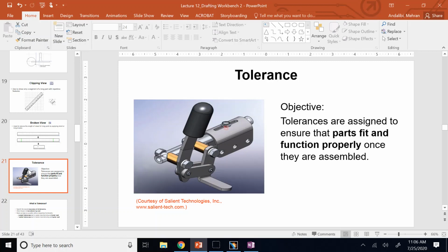So if it's very marginally off, it can still work, but probably you see what we call clearance and a little bit loose of connection. But maybe that works, maybe not, depending on how much you're allowing the manufacturer for inaccuracy. They have to observe that and make sure that they make the part with that much of accuracy requested. Because if they don't, then the part is useless. You have to throw it away. It doesn't work for your application.